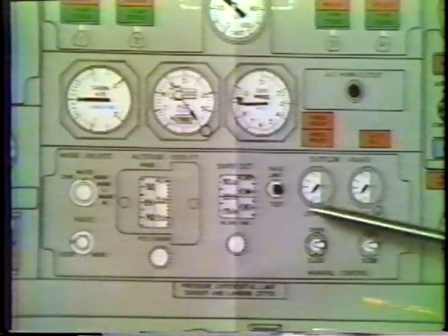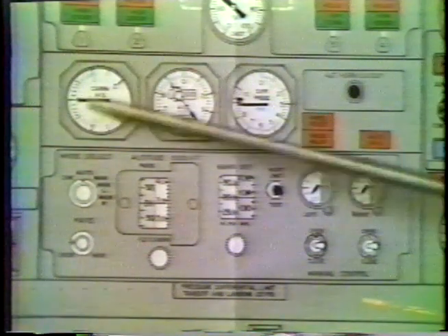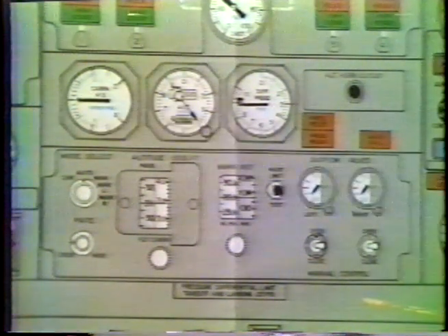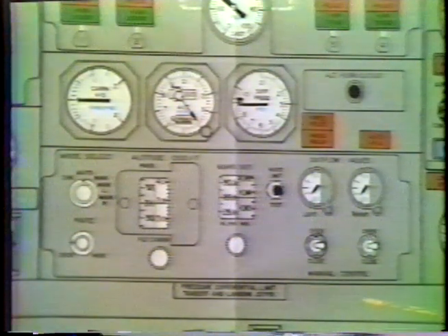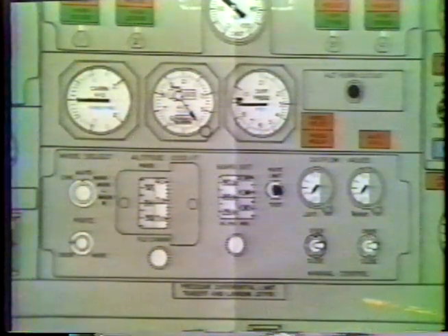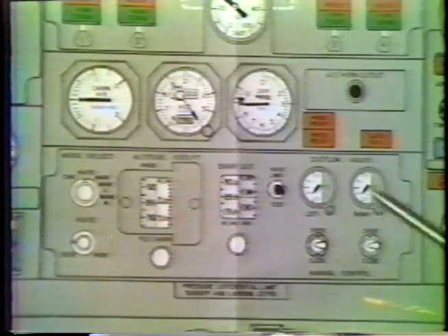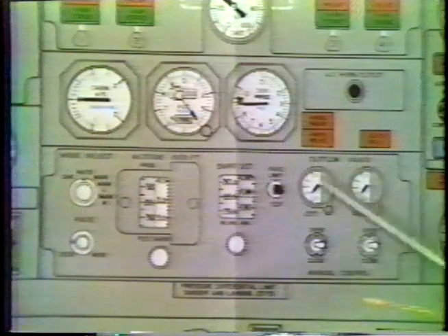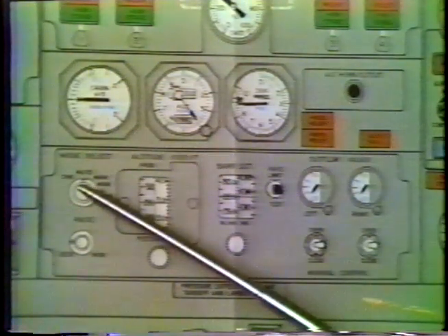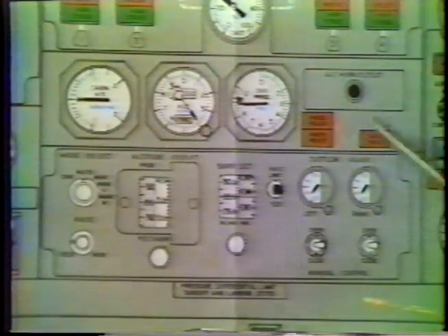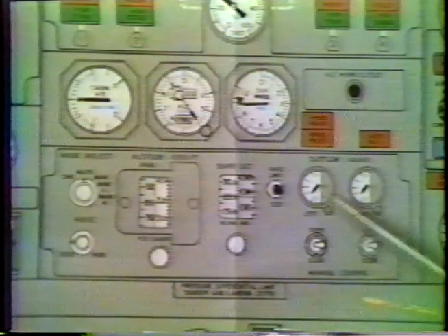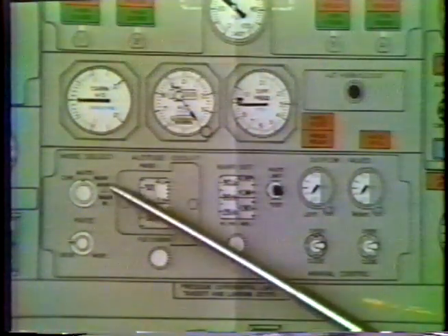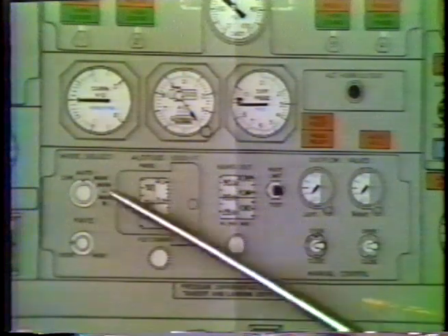The outflow valves will oscillate, and the cabin rate of climb will go as high as 1,000 feet per minute up and down, and the cabin itself will gradually pressurize under the auto fail mode. To get control back again from the auto fail mode, the mode selector has to be moved out of auto into manual. That will put the light out. Now, it's a possibility you could go back to auto again and operate under auto. If that isn't available, then you would have to go to manual, manual left, or manual right.